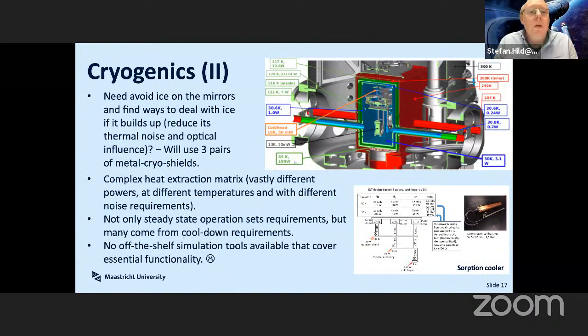Okay, so obviously the cooling is one of the key parts. We want to reduce the water. Fulvio mentioned already, you don't want to have MLI in there. So what we have here is actually 3 pairs of shields. These are just aluminum sheets, but a few hundred kilograms in total, which sit here on top of a liquid nitrogen vessel to cool the intermediate shield. And the inner one will be connected to a pulse tube cooler.